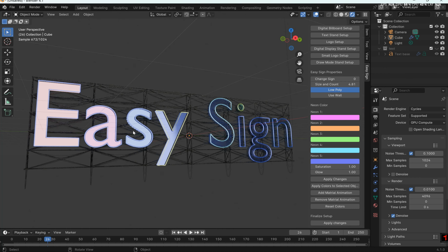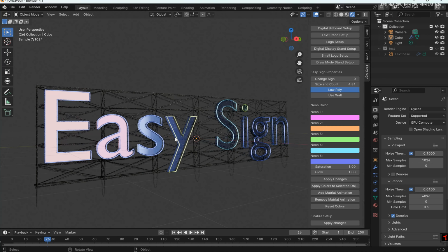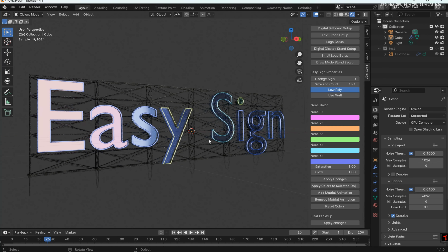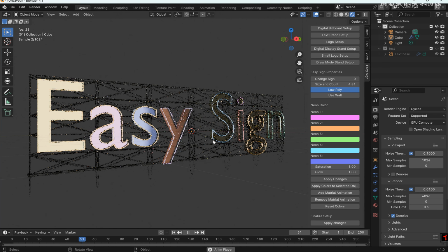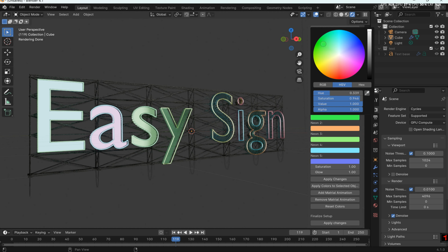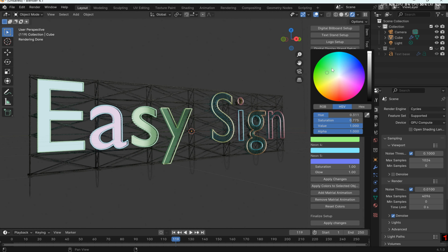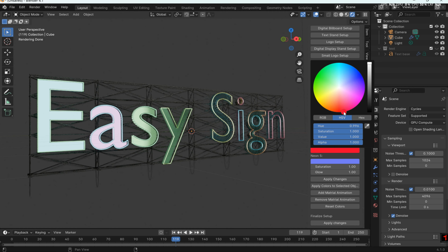That's it for now. The next section we are going to talk about is the material section. Take a look at this. I go on render mode. I think we are on Eevee here. Yeah, one quick tip here. If you are on Eevee and you want to render, you have to know that there is only one solid color, and if I hit play, all of the objects will have the same color.